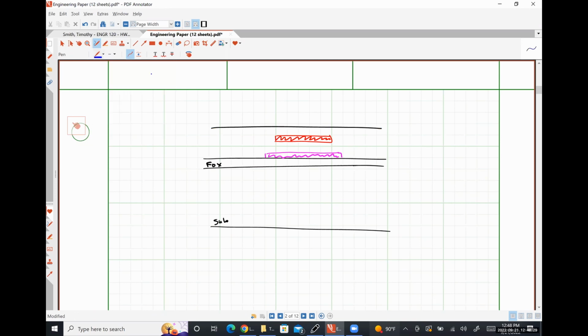And then up here, we have a run of metal 1 that we're going to use the contact layer to make contact with the poly 1 layer. And then over here on the right hand side, we're also going to have a run of metal 1 to make contact to the poly 2 layer. So up to this point, we know about our poly-poly capacitance, C poly 1 to poly 2.